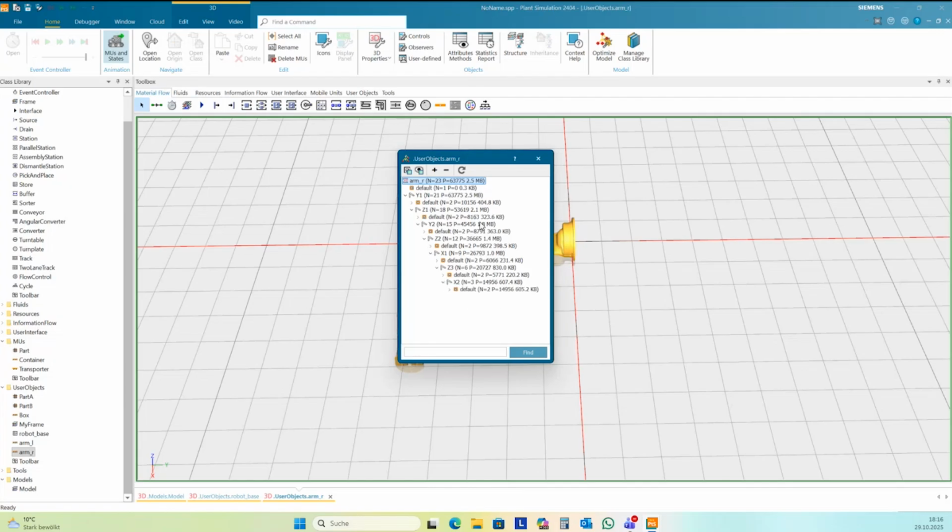If you download such a robot, then you need to change the flat structure of the robot from the original graphic into such a hierarchy with animation or animatable objects at each element here. And for each element, you need to define a joint and a joint configuration.